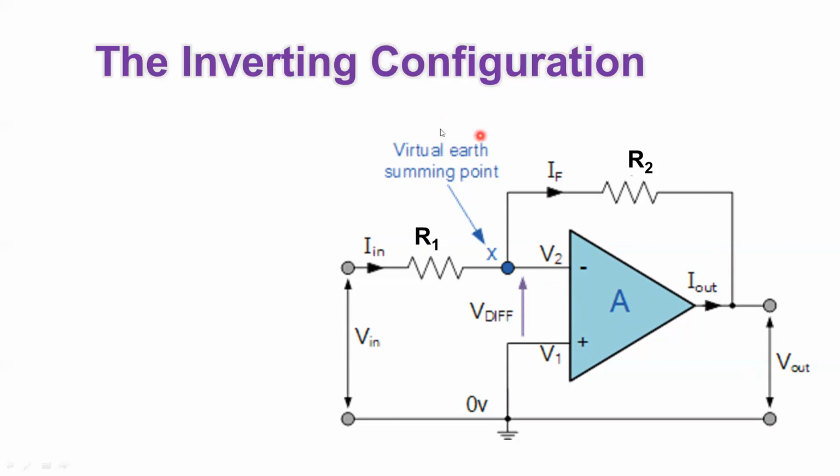So this is a very important definition in our operational amplifier circuits: whenever you have one terminal connected to the ground, the second terminal will automatically be at 0 voltage, which we call a virtual ground. Now, as I mentioned earlier, no current is flowing here, no current is flowing here. So you can easily assume that the only way for the current is to flow in this direction.